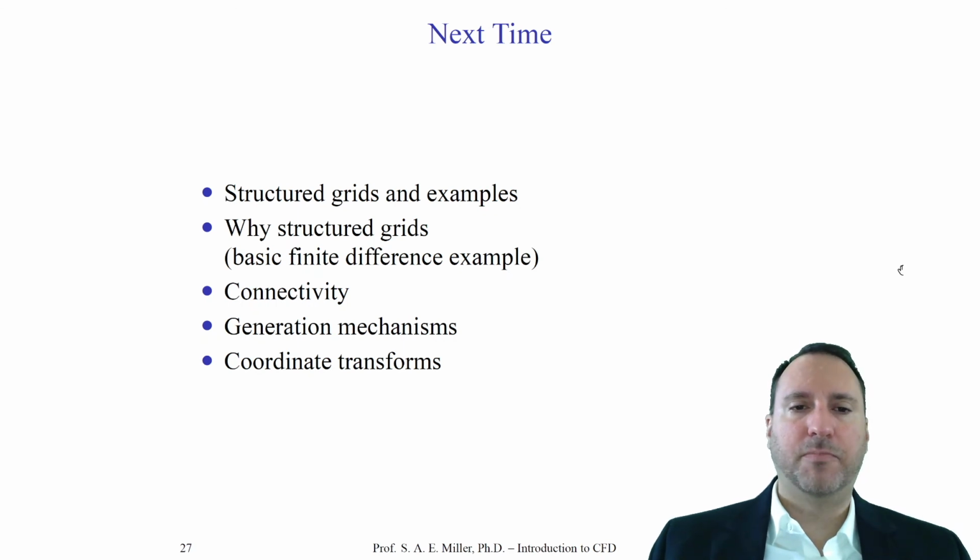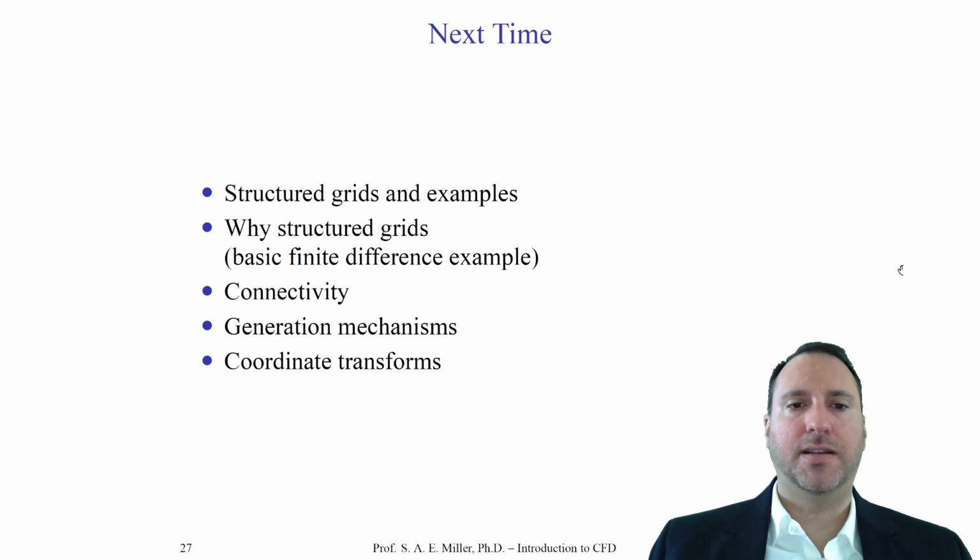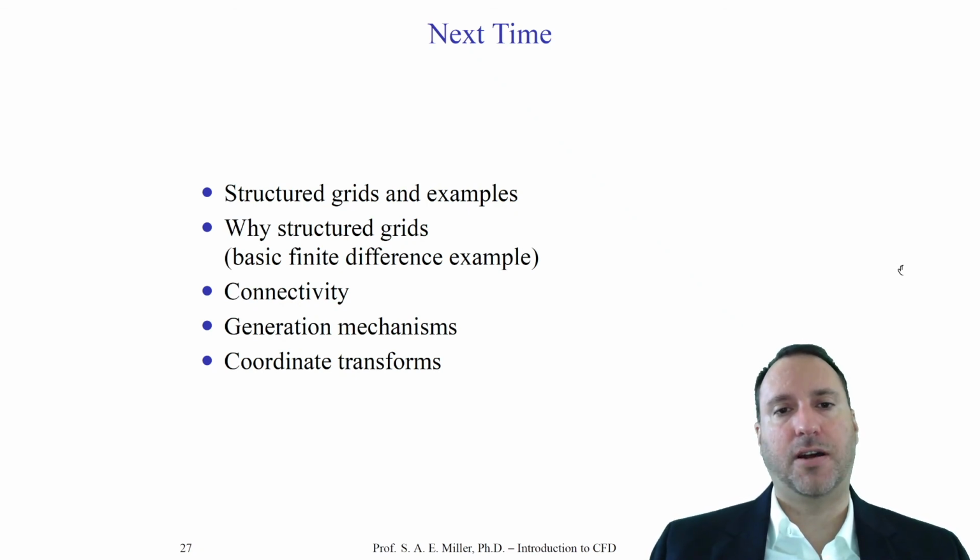We'll also show some more finite difference examples. We'll talk about the implied connectivity of structured grids, and we'll look at some algorithms for generating structured meshes. Some can be as simple as a few lines of MATLAB or Fortran or C. Other times it can be very complicated and almost as complicated as creating an unstructured mesh. And they are certainly more time consuming for you, the user, to create a structured mesh than an unstructured mesh. This is one reason a lot of companies and research organizations have moved to unstructured meshes, because they're easier to create for complicated geometry than a structured mesh.